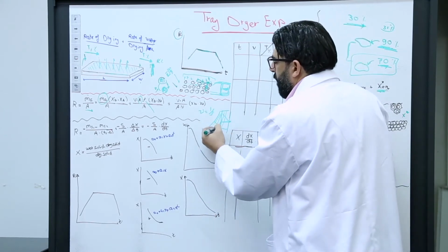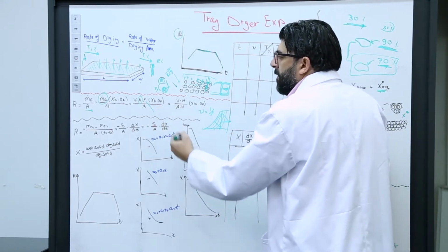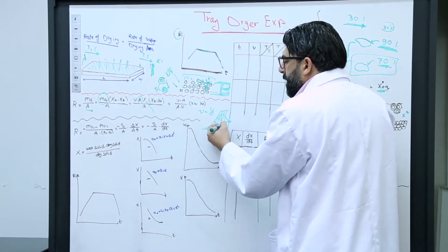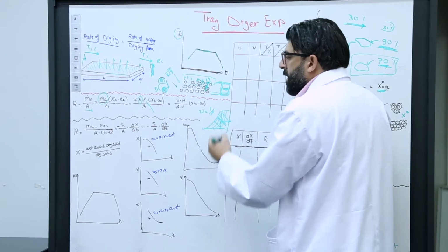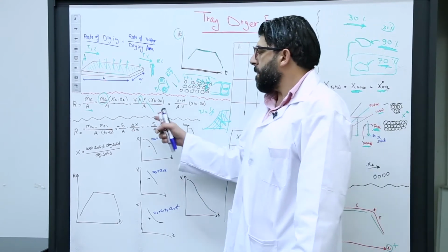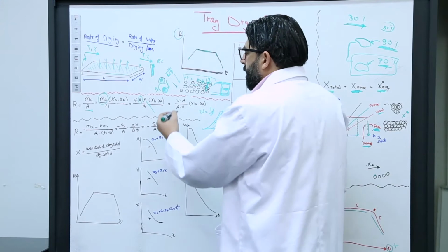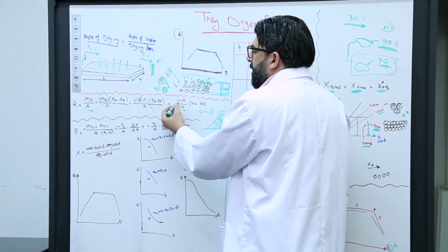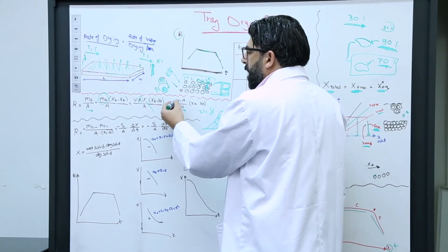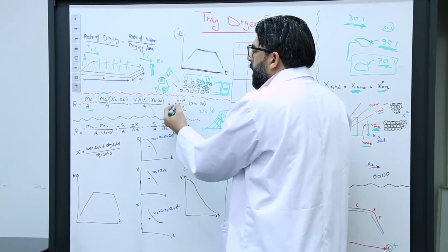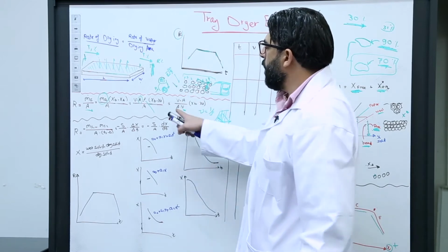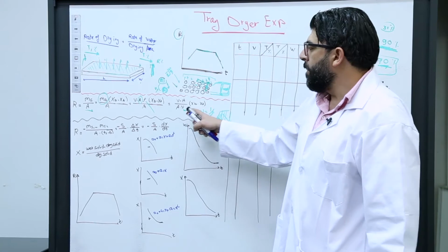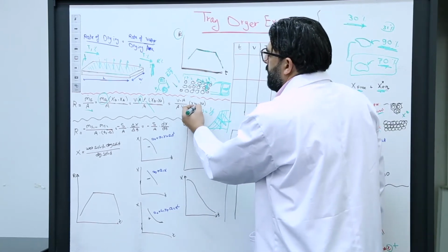So here's specific volume. You can find the specific volume of the inlet air and the specific volume of the outlet air, and the average of them is the specific volume of the air. So here rho will be down here, specific volume. We have here again the speed or velocity of air, the cross-sectional area of the duct, the drying area, and the specific volume and XP minus XA.